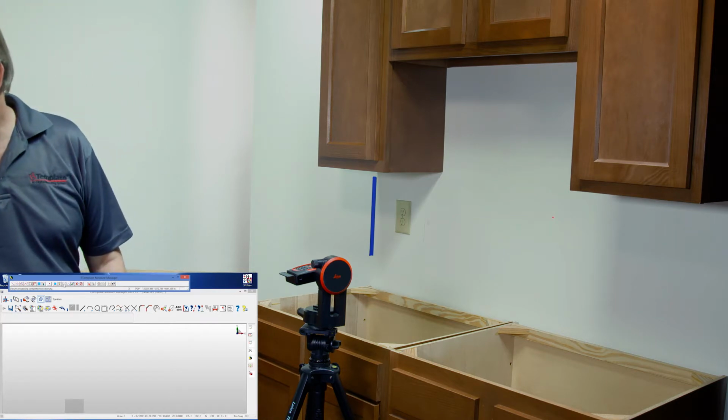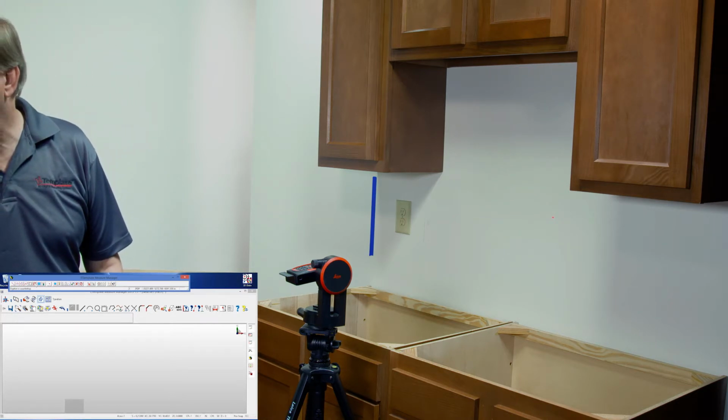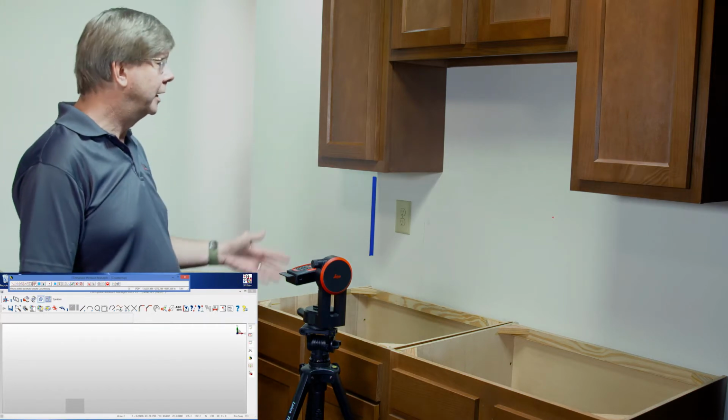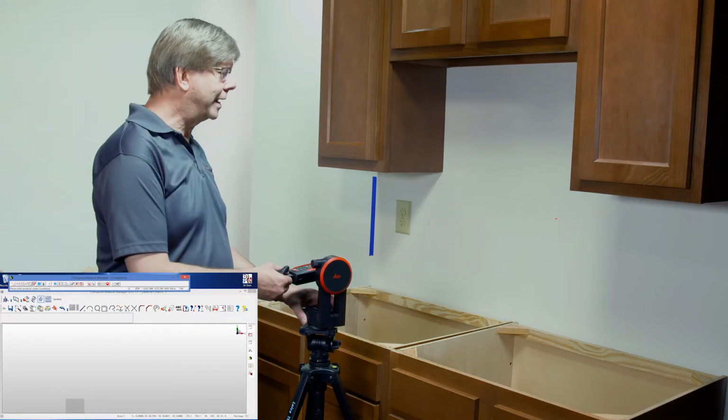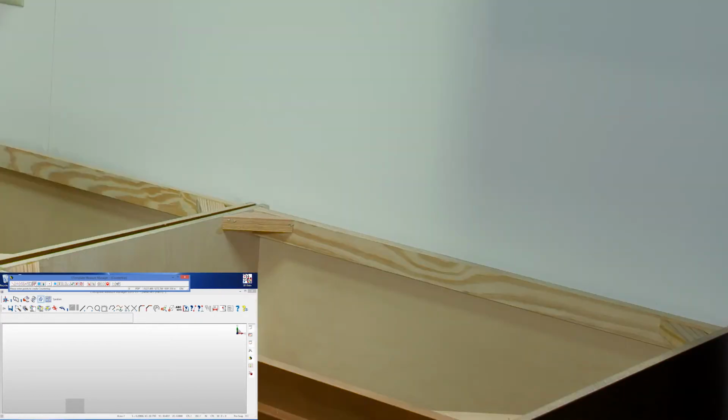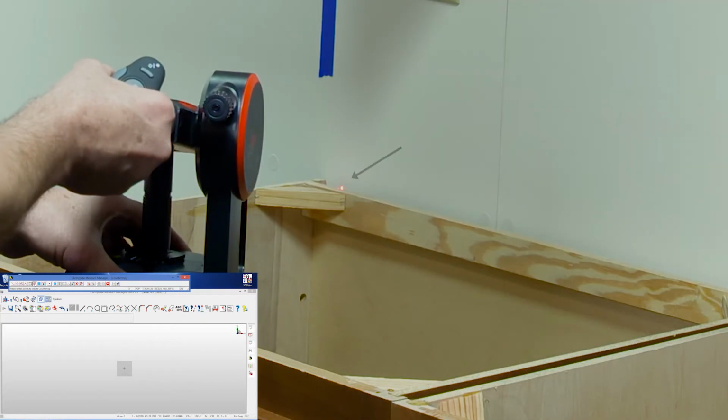And now, there are several ways of measuring full height splash. You can just measure it as independent lines. In this case, I'm going to actually measure it as a countertop with 0 overhang and 0 radiuses, all that being done in my settings file. So I'm going to take points, 2 points per edge, moving around.